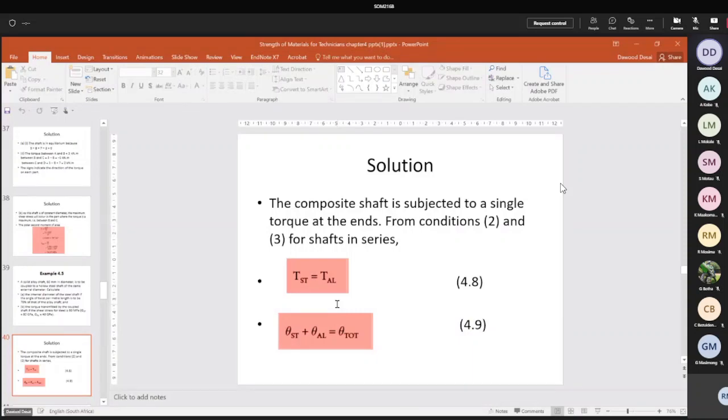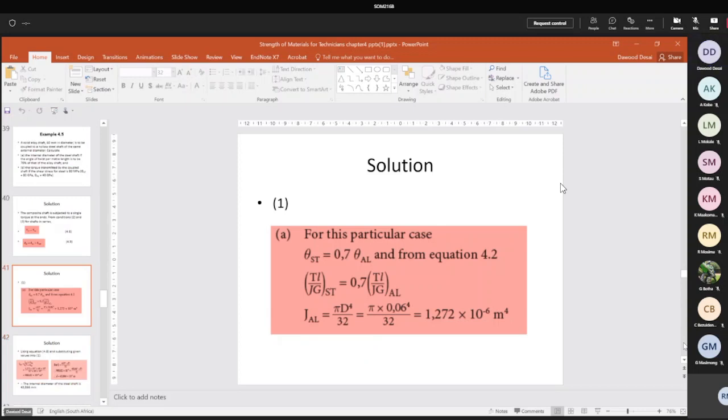See that same thing as at the top. Total angle of twist is summation of angle of twist on each section, like your textbook is also showing you. End loads, the torques are the same. How we had yesterday, the force is the same throughout the shaft. If it's end loads, same thing here. Very easy, eh? Right, because here they're writing it mathematically.